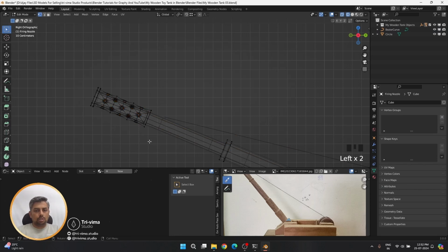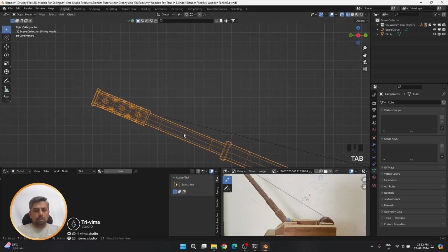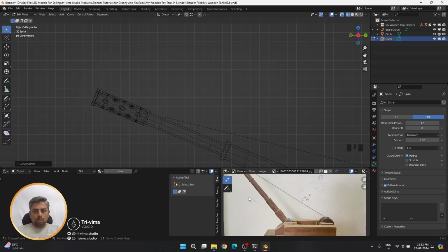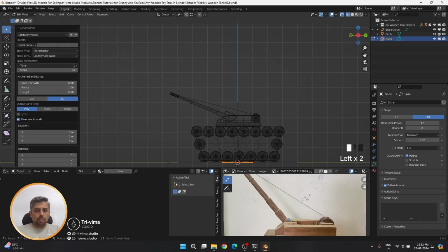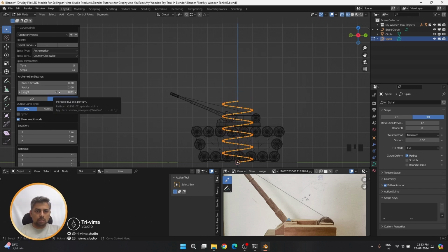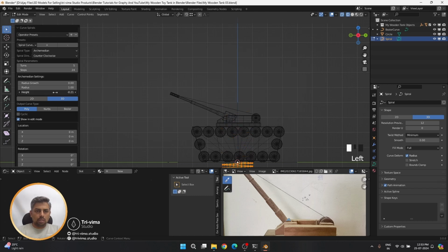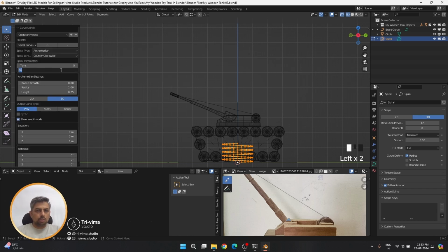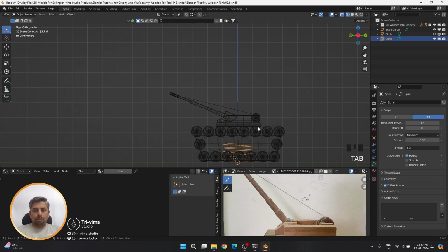Now if I select this edge, it's not taking because the edge is there. So I'll create a curve. In that curve, let's have it 5 down, and the height, I think this is good, 0.25 height, and then let's use this for a resolution step of 12. That's enough. Even though 8 is also good, I think 12 is a must. Now this will be used everywhere, here.